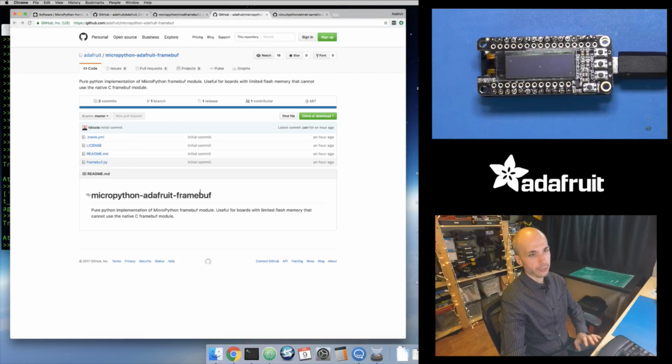because for some boards that run CircuitPython, like the SAMD21 Feather M0 Basic, any of the boards that don't have an external flash memory, you might not have the frame buffer module compiled in. And so if you get an error that says error importing framebuff, check out what I just showed in this video, check out this module, add this module, and things should work. You should be able to do all the same graphic drawing, your code should be exactly the same. It's just going to be a little bit slower because it's this trade-off here for speed.